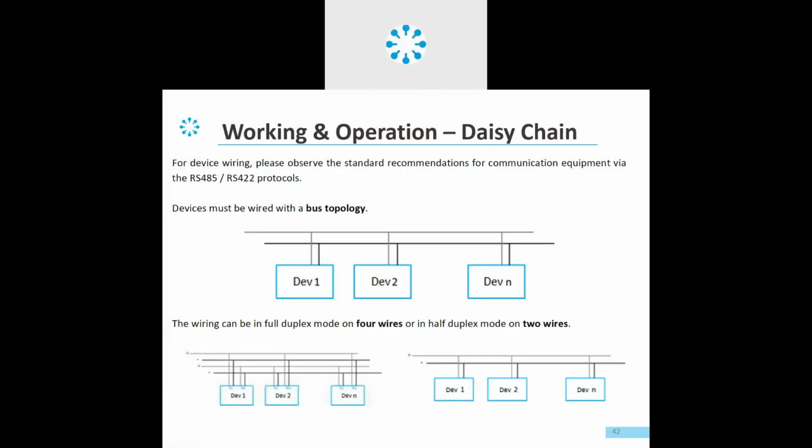So for the daisy chaining, how it should actually happen. For example, consider this as a meter or a sensor. You have a chain coming, you have data plus, data minus. You have data plus, data minus connected. You have another chain going out from those same ports, again connecting on another meter or a sensor, data plus to data plus, data minus to data minus, and like this.